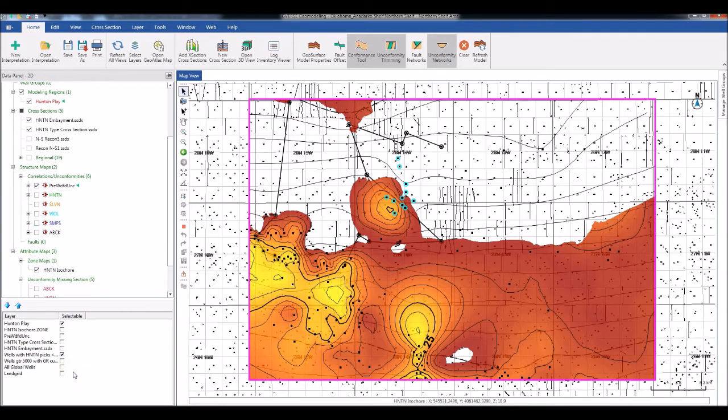Apply the relevant modeling tools and observe the effect. Graphically add more wells to the interpretation in the area where you want more model definition. Create and interpret more cross sections until the play is fully defined. If desired, use modeling regions for better local performance and definition.